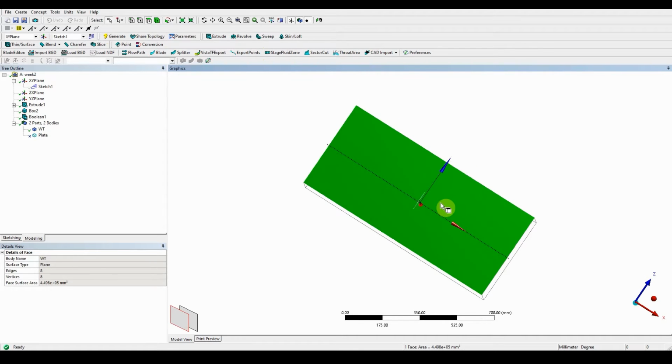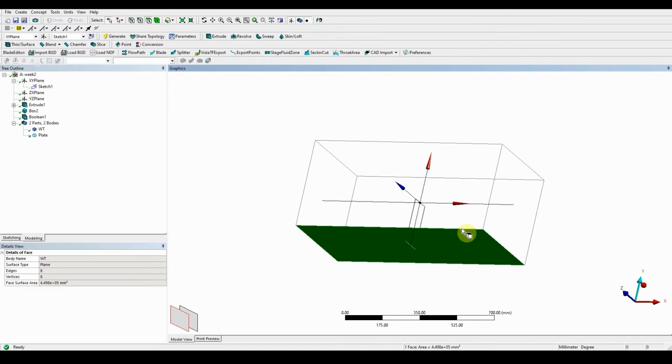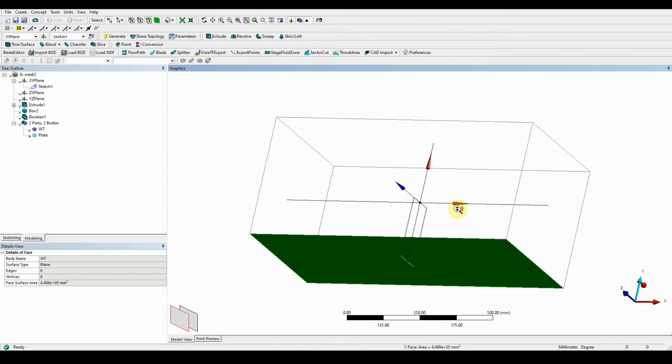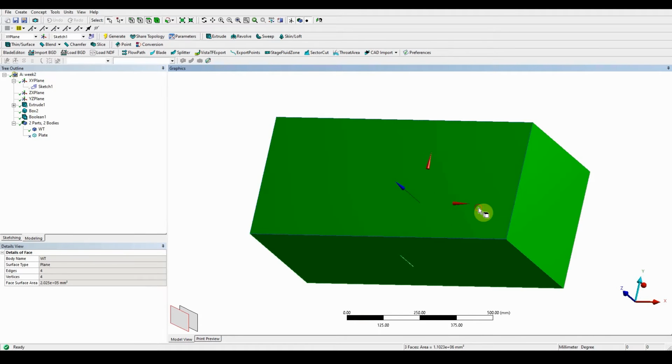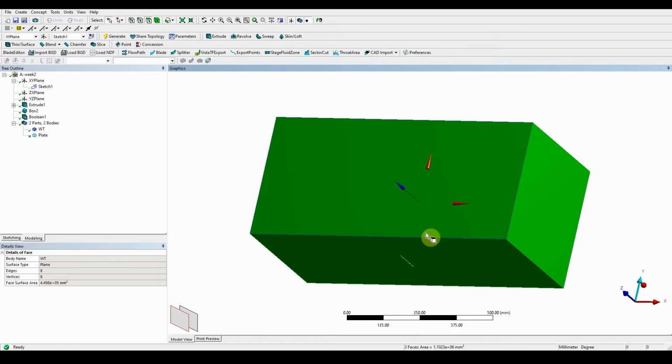So what I would say is the middle mouse button spins your model, the roller up and down zooms in and out. Now if you use the keyboard as well, so control left click is multi-select. You can see here where I'm selecting the faces, because I've got faces turned on. At the moment, if I do it that way, individually I can't. Press control and it can multi-select.